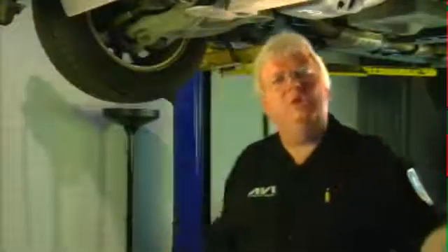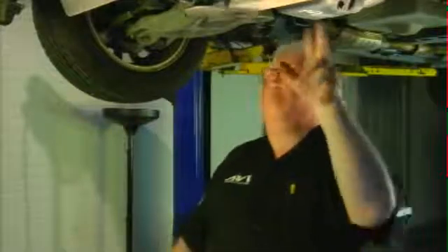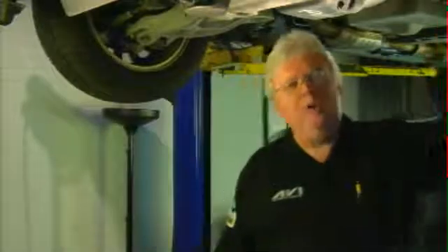Also, while you're under the vehicle, make sure you check power steering lines that may shoot off to a power steering cooler. It looks like this vehicle may have one. And just general inspection. Just use your eyes. Use every sense that the good Lord gave you. You can hit suspension components with a big mallet, a soft mallet of some kind. Just give it enough of a rap and see if you can hear a vibration.